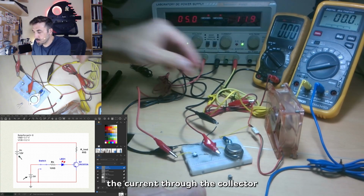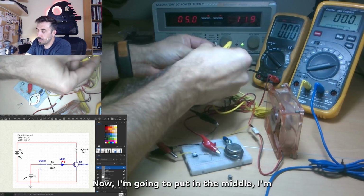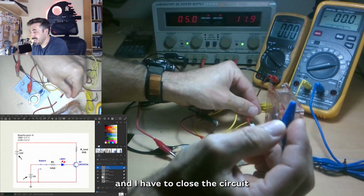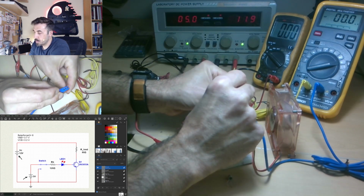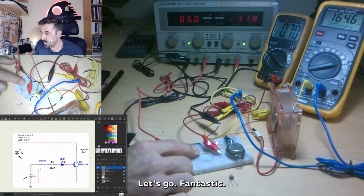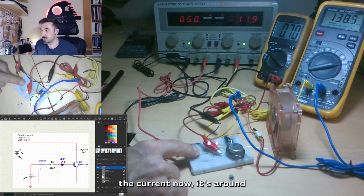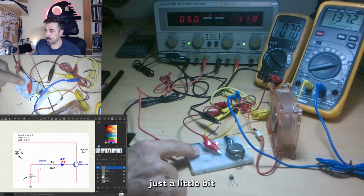Now, because I want to measure the current through the collector, I'm going to break the circuit at the collector, put the ammeter in the middle, and close the circuit at the place that I broke before. Right, so, done, and let's go. Fantastic. So here the current now is around 150 milliamps, which is the one that we computed before, just a little bit less.